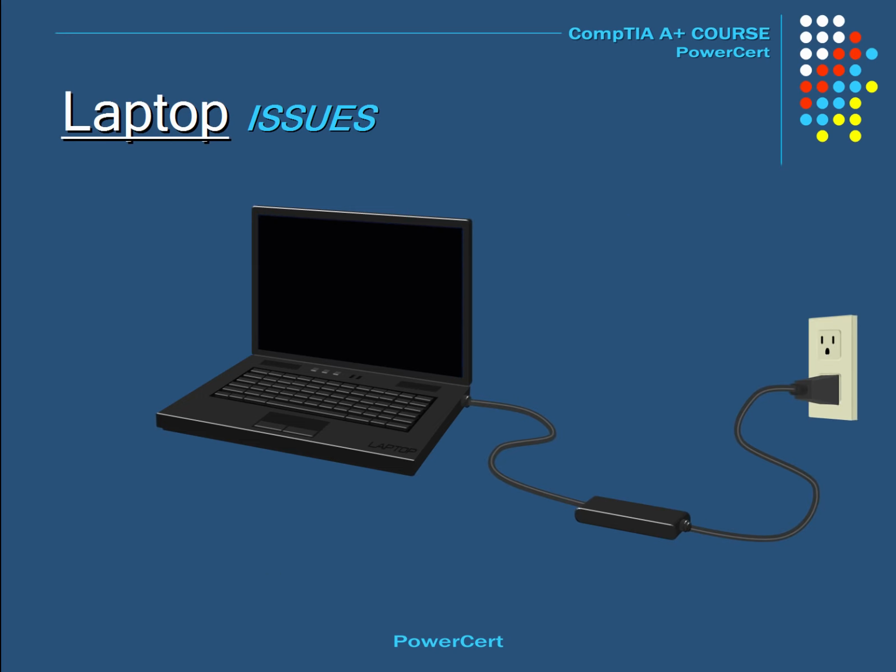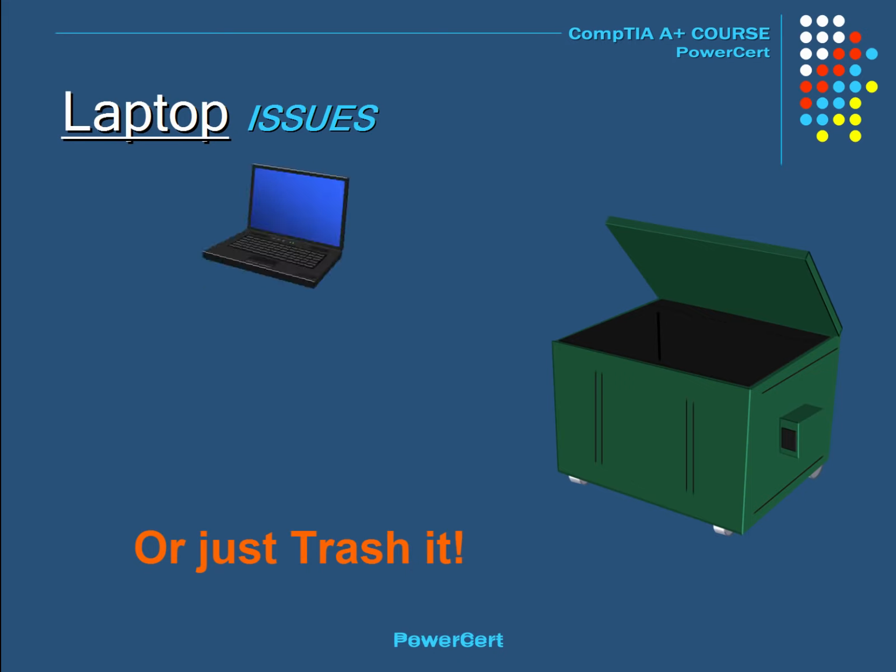Now, if you press the power button on your laptop and nothing happens, in other words, you don't see any power LEDs, your screen is totally blank, and you don't hear any fans turning, well then one of the first things to check is to make sure that your battery charger is plugged into the wall and at the other end is plugged into your laptop. And once you verify that and still nothing happens, then most likely you have a dead laptop. In other words, the motherboard is dead and needs to be replaced.